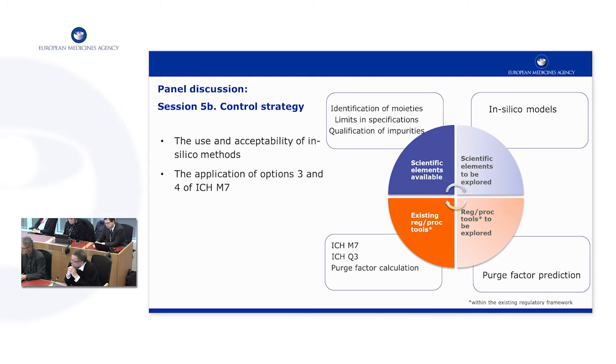I know that certainly as part of our change control process that we have around all of our established products, that's entirely ingrained within our written procedures internally, that if you make changes to your process, particularly, for instance, a new route would trigger it. We would have to do a full-blown assessment of that. But the expectation is that even if we're talking about changing a solvent or something like that, then that would at least go through a preliminary assessment to see whether or not that could either change the actual basis and argument of the actual purge argument, but also whether or not it could introduce a new impurity.